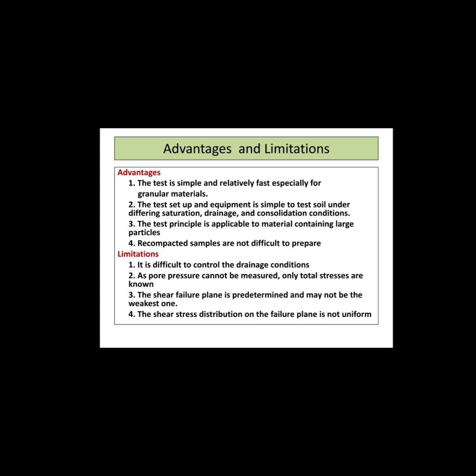Now let us look into the advantages and limitations of direct shear test. There are many advantages. The test procedure is simple, relatively fast, especially for the granular materials. The test setup and the equipment is simple to test the soil under different saturation, drainage and consolidation conditions. The test principle is applicable to the material containing large particles. The recompacted samples are not difficult to prepare. The quick drainage of the pore water in the sample is usually easy to achieve because of the thin depth